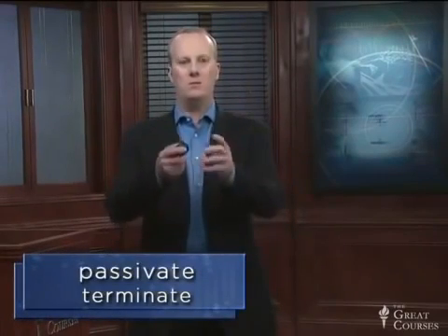The other thing we love about it is that that oxide is just inherently disposed to passivate or terminate the states of the silicon that is sticking out of the substrate, sticking out of the wafer. And so we have a natural strategy using silicon's own native oxide for passivation, for termination of these sites chemically, and for the formation of an oxide of essentially whatever thickness we want to grow it to. We just take a bit longer, we just increase the temperature a bit in order to grow a more complete oxide. Now, here's where things start to get challenging.